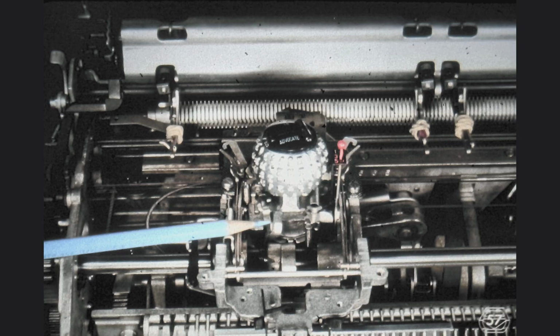Here is the sequence for the detent motion adjustments. First, we position the detent cam on the print sleeve sideways, so that the skirt clearance equals 0.89 of a millimeter. Then we adjust the height of the detent actuator lever, so that when the detent cam follower is in the dwell of the detent cam, we obtain the 0.25 millimeter clearance at the indicated point. Occasionally, we might have to readjust the skirt clearance after making the adjustment to the height of the actuator lever.